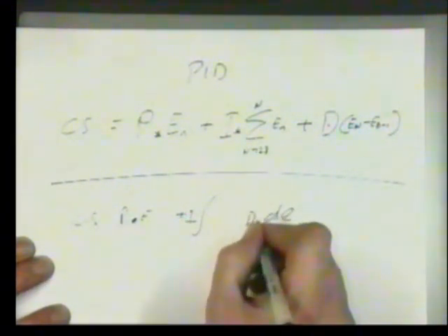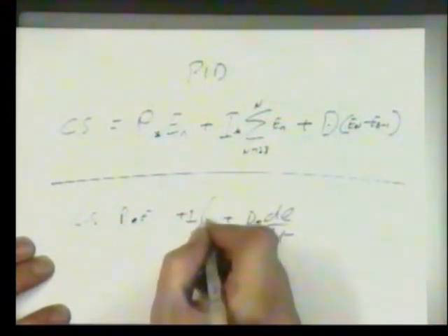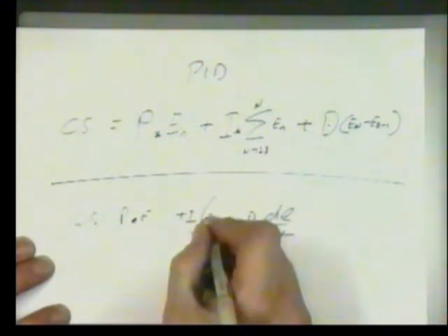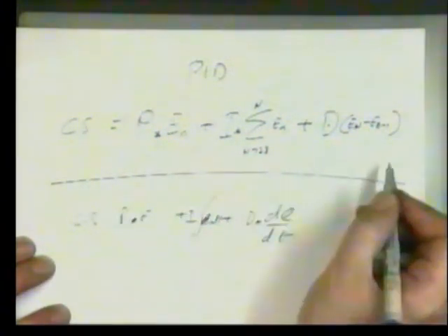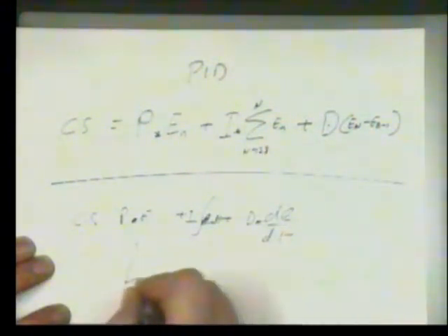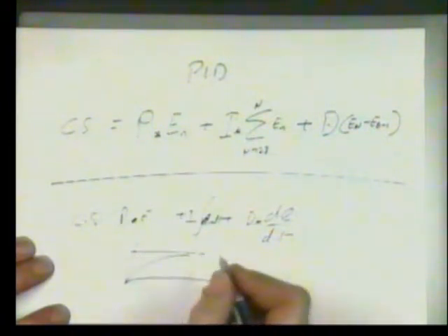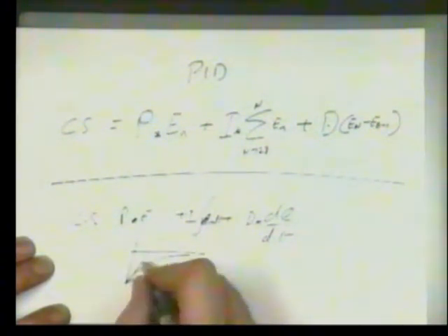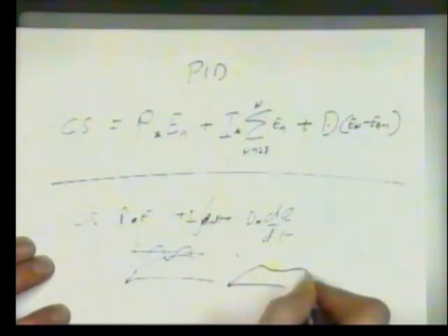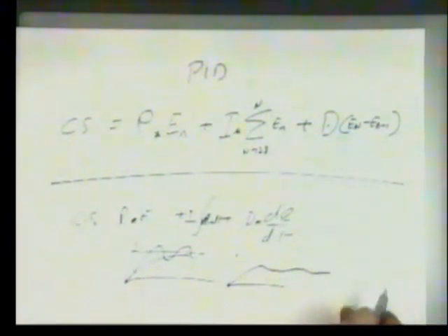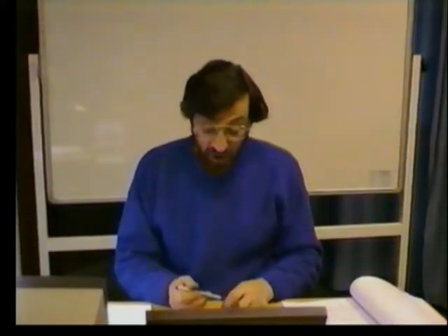It's exactly the same thing, as long as you understand how it works, what each of these terms are, what each of them will do, how they will affect the response characteristics to go from steady state error, proportional, to the integral, to the derivative, which will tend to slow down the integral term to bring it under control. That is the essential requirement. Three-term control, proportional, integral and derivative.